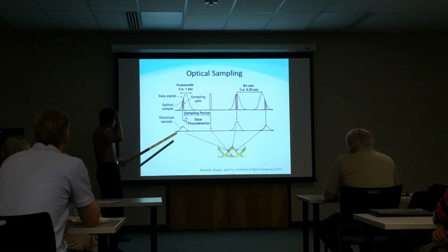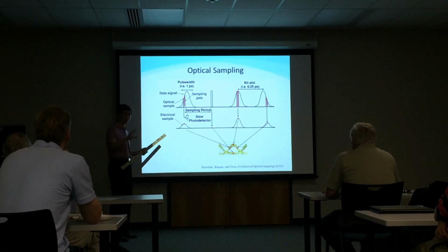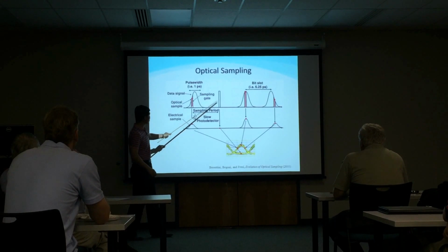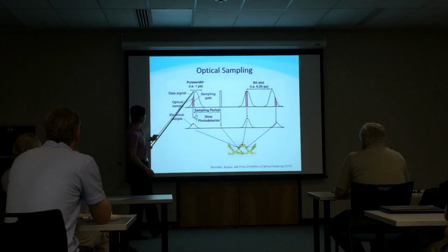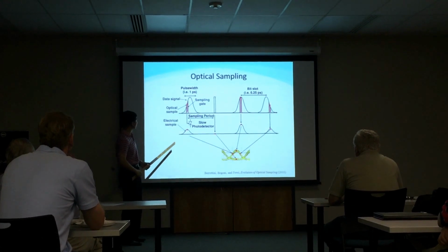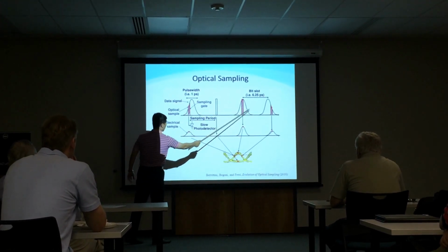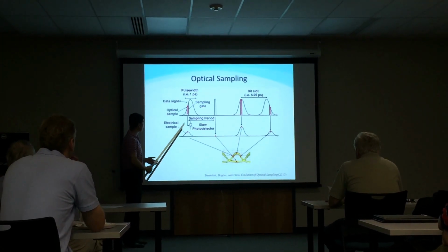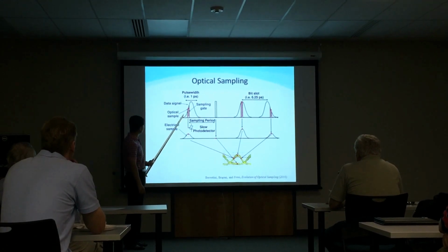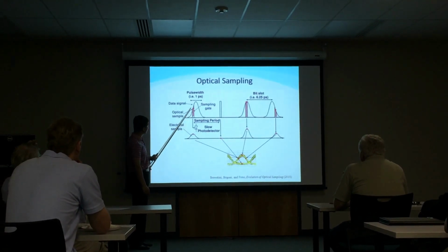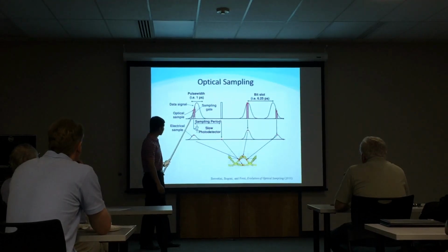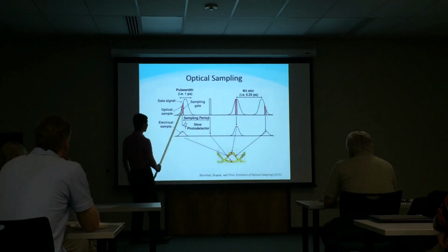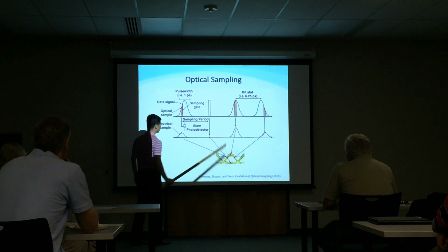What optical sampling does is a lot like electronic sampling, like the sampling oscilloscope. Basically, you set up, for example, a quasi-periodical optical signal, these pulses. Then you somehow create these very short gate signals. You don't have to probe the profile of each pulse, but over many periods, these gate signals map out the overall envelope of the optical signal.